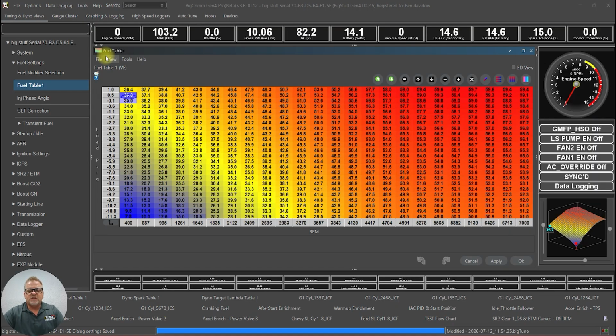Welcome to another Big Stuff training video on our Gen 4 ECU application. So in today's video, we're going to be going over how to configure the electric fan outputs as well as configuring them for pulse width modulation use. If you go into the software, there's a couple things we're going to go over on how to actually configure and set these up.